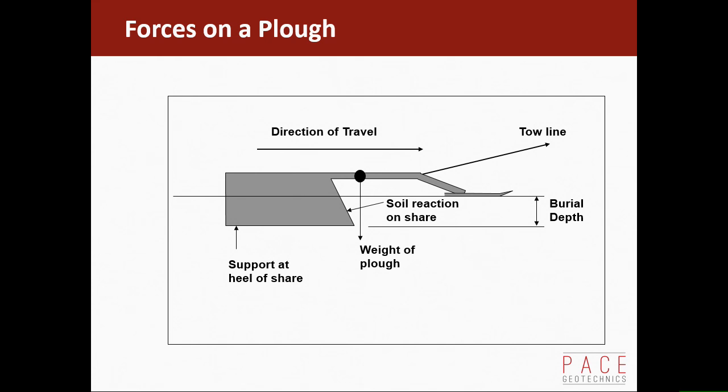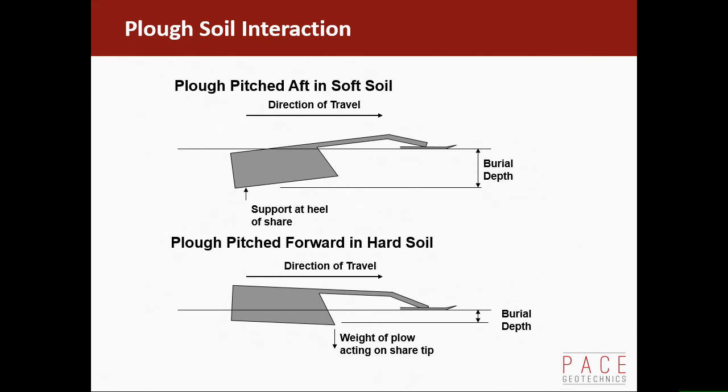Just to talk a little bit about the forces on the plough and why it is beneficial to how a plough deals with different soil types. You have a soil reaction on the share, which is sort of pulling it into the seabed, but the plough at the back is being supported there by the heel of the plough. Now the good thing about that is if you're in soft soil, the plough will do what we call pitch aft, sort of sit down, and it will create a slightly deeper trench, but it's being supported there.